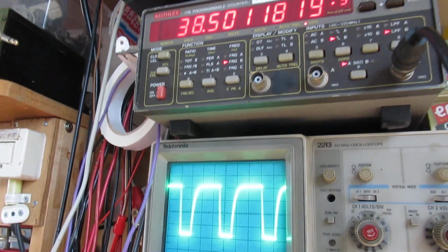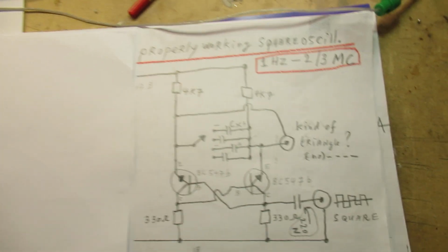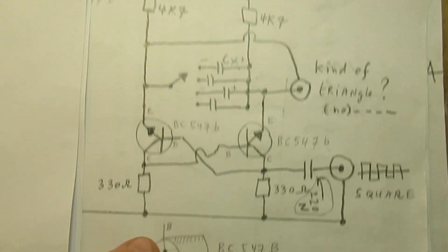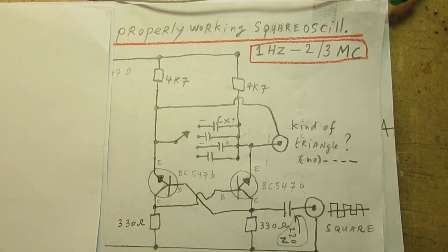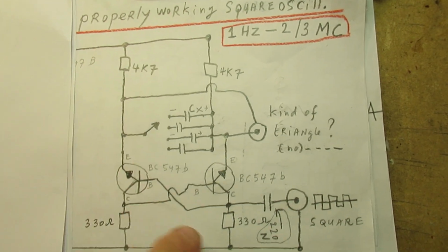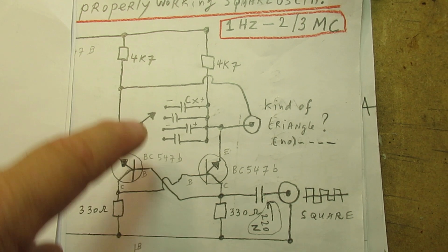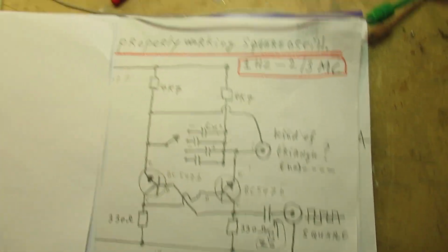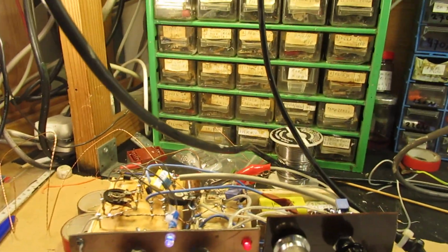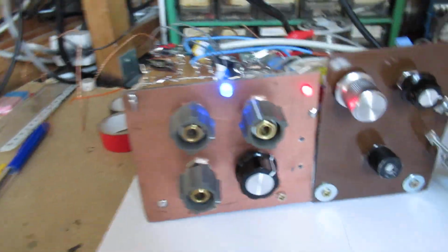And of course, that original schematic of the 1960s was made in such a way that the oscillator could not switch off. But of course, when you use potentiometers here, the oscillator will stop when the oscillating conditions set by all these different components, and I mean especially the resistors, the variable resistors, are changed. That means that you need an indicator that the circuit oscillates, and I've made it here with the blue LED.